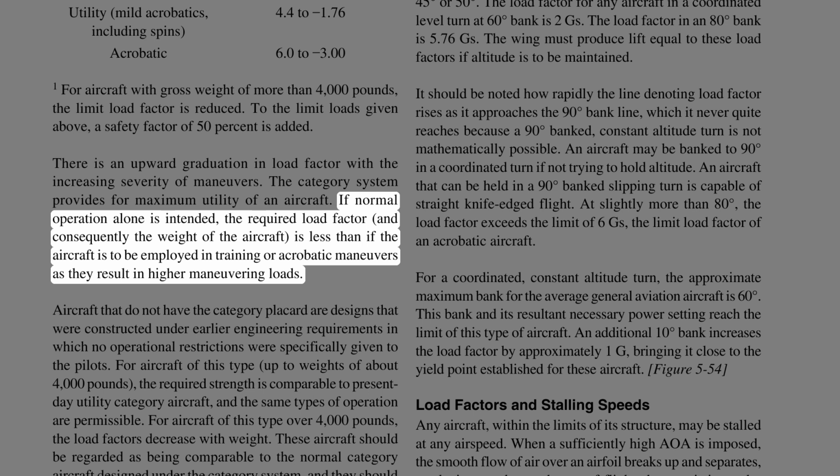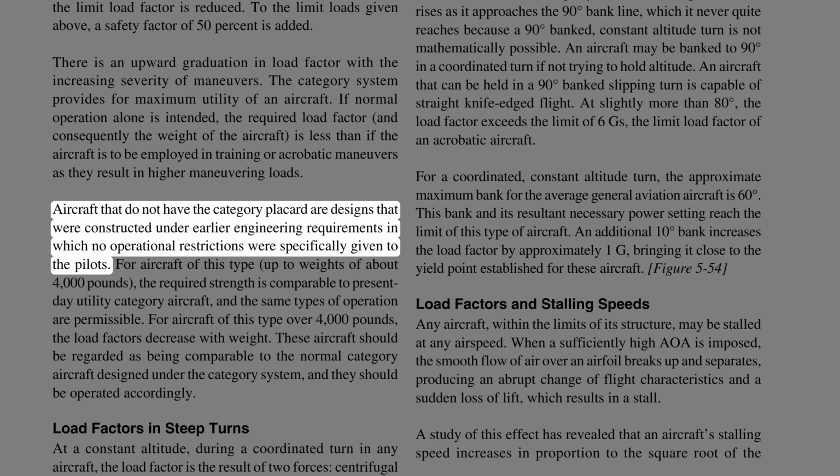If normal operation alone is intended, the required load factor, and consequently the weight of the aircraft, is less than if the aircraft is to be employed in training or acrobatic maneuvers, as they result in higher maneuvering loads. Aircraft that do not have the category placard are designs that were constructed under earlier engineering requirements in which no operational restrictions were specifically given to the pilots.